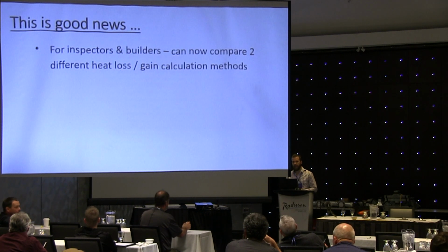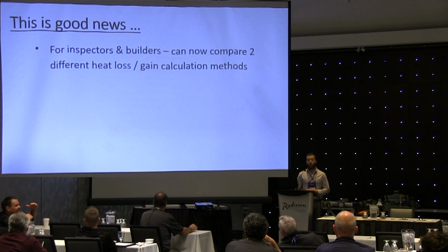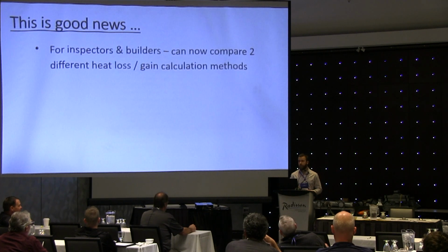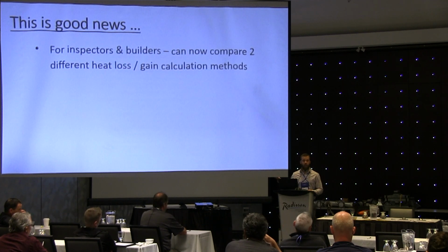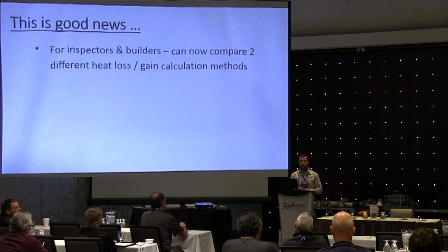Okay. Yeah. I think that 30% higher on the mechanical. What we're looking for here is to catch installations like David said his house is, where you have a contractor that was thinking 100,000, but the energy modeler gets 25. Now you put those two in conversation, and you're going to learn the mechanical contractor did not do a heat loss. Once they do, if they've done it right, their value should be very similar. That's what we're trying to weed out with this.